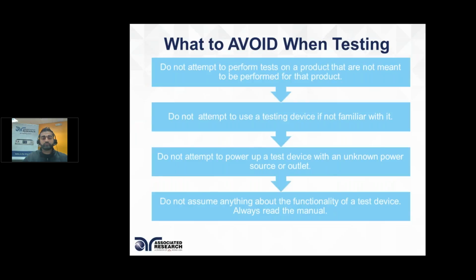Here are the things I talked about in more detail. We do have some points that we make here about making sure you know the product you're testing, making sure the installation you're testing is not overstressed, understressed, or making sure the test is meant for that product. You also want to be aware of the tester itself, the output capacity of the tester. Is it able to output 100 milliamps of current? Is it able to output 5,000 volts of voltage? So you want to know what the tester is able to output, and also let the operators know the inherent capacity of the tester.